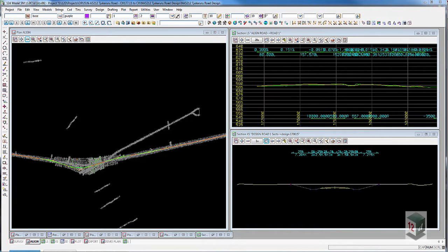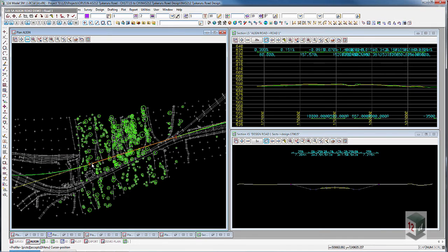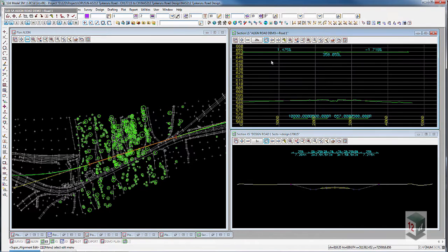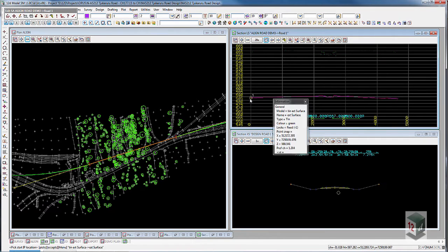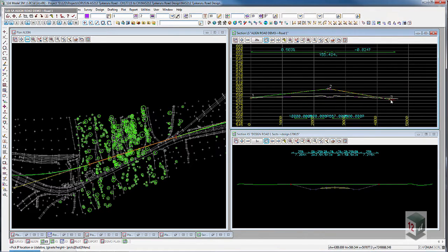We then move on to the vertical geometry. To do that I must first view the section of the alignment. And what you see there is just no vertical geometry over natural surface. And just like horizontal IPs, we can decide the vertical geometry by clicking the IPs.